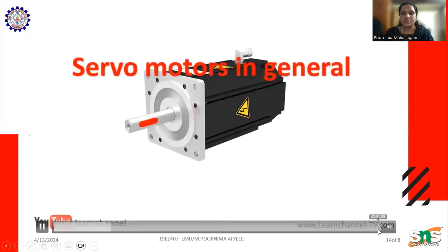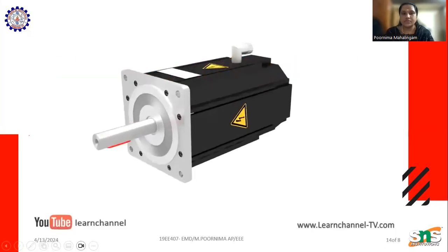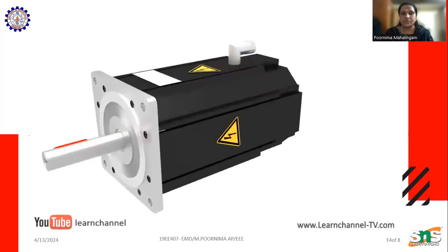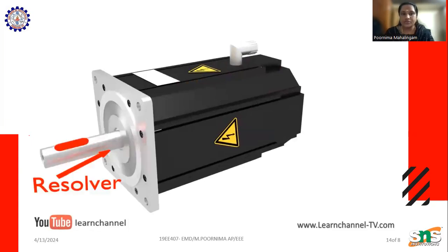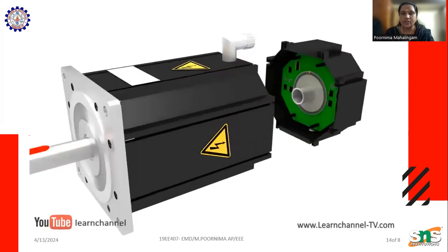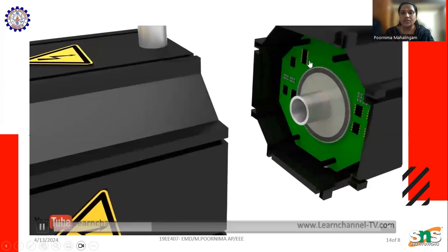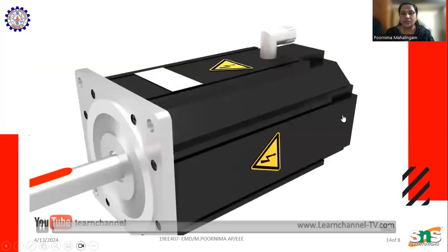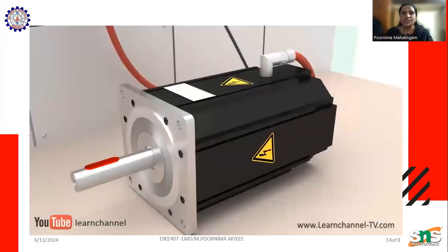The servo motor is a part of a servo drive, whether brushless DC motor, synchronous, or a robust asynchronous motor. But one thing in common is the detection of the rotor position by a sensor. It's either a resolver or an encoder. In this case, you can see that encoder. This sensor input device gives feedback to a controller, for example, to keep the speed constant, or to raise the target position as fast as possible.